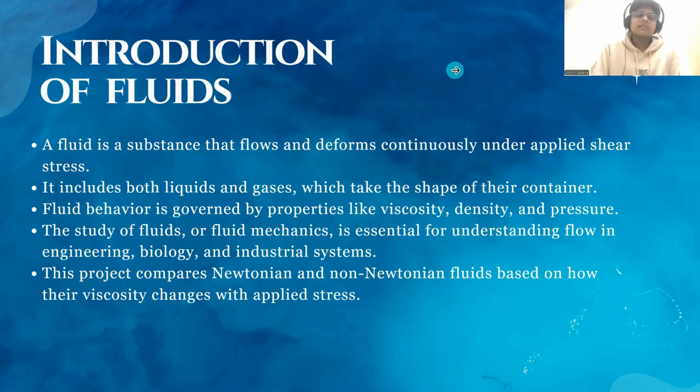Let's start. First of all, giving an intro about fluids. A fluid is a substance that flows and deforms continuously upon applied shear stress, which is force. It includes both liquids and gases, which of course take the shape of their container. Fluid behavior is governed by properties like viscosity, pressure, and density, and the study of fluids, or fluid mechanics, is essential for understanding flow in engineering, biology, and of course in industrial systems. So our project compares Newtonian and non-Newtonian fluids based on how their viscosity changes with applied stress.